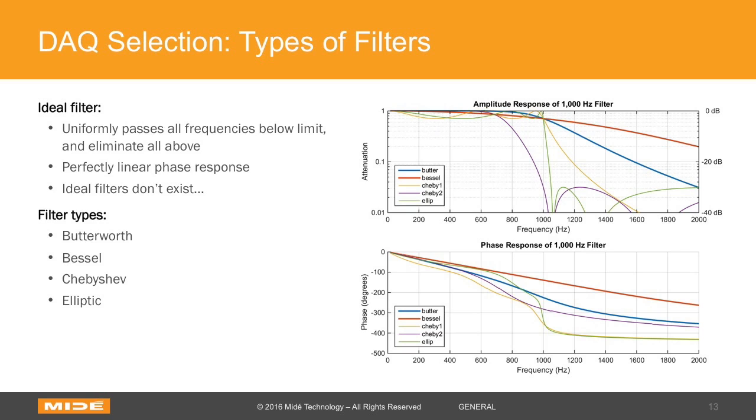So generally, the higher the better. But the key takeaway here is Butterworth is for vibration testing and Bessel for shock testing. And generally, don't touch Chebyshev and elliptical unless you know what you're doing and really only interested in the amplitude.